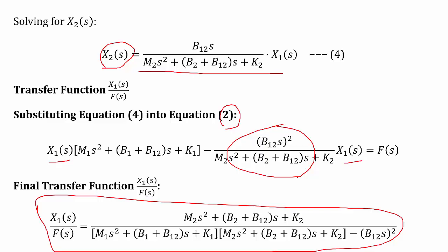So initially, by seeing the diagram, the system, we first have to note how many masses there are. Based on that, we get the number of nodes. Based on the number of nodes, we draw the free body diagram for each node, and see how many elements are connected. Those elements are mentioned as the opposing forces, and we have to consider the mass's own opposing force, and see whether any applied force is there or not.